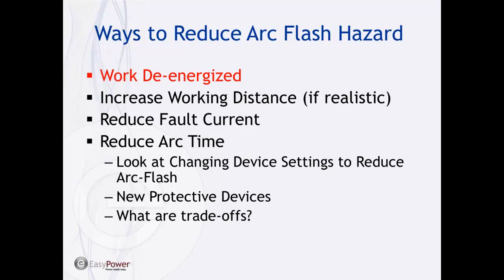So there are three ways that are listed. The first is probably the easiest: just by increasing your working distance, you can reduce the incident energy. It's not always practical, but it is something that can be done for certain work tasks.